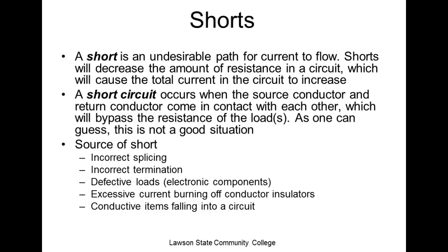Shorts are bad. A short is an undesirable path for current to flow. So you still have current flowing. It's just not flowing in the path that it was intended to flow. Shorts will decrease the amount of resistance in a circuit, which will cause the total current in the circuit to increase. A short circuit occurs when the source conductor and the return conductor come in contact with each other, which will bypass the resistance of the loads. So the only thing you have is the limiting resistance of the circuit.